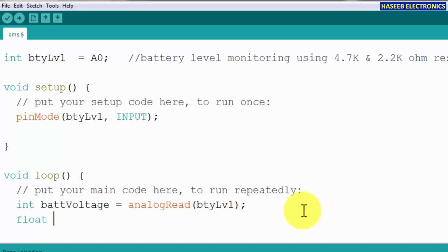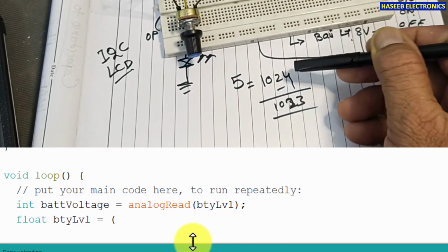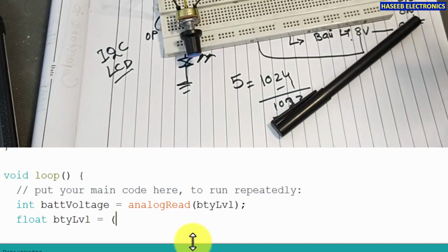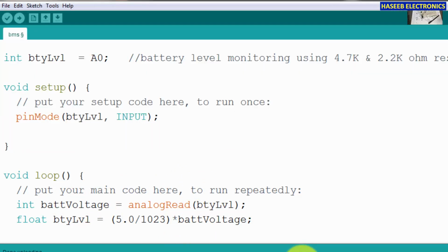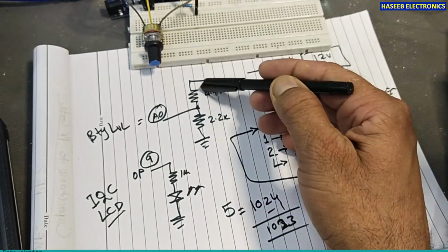Now float, calculate it. Float battery level, what is the battery level? That is equal to, make a calculation: when we apply 5 volt to the input, at that time it will convert it into 1024 bits. That will equal 1023, because 0 is also included here. So we will say 5.0 divided by 1023, multiplied by this value which we measured from the battery terminal. Terminate. We calculated the voltage. Now one thing to understand: when we connected this battery, we connected it to a voltage divider network.